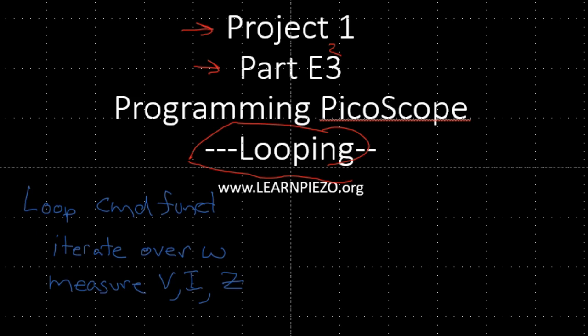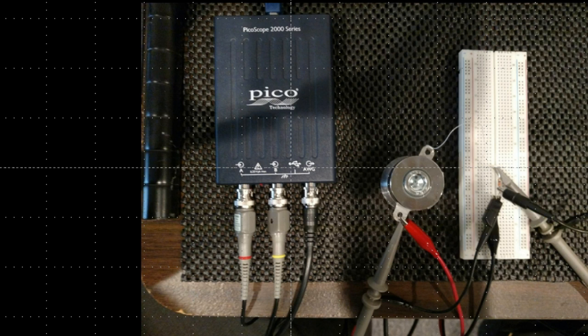So let's first go into the experimental setup as you see here. We have our Picoscope. We have channel A, or channel 1. We have channel B here, and we have the arbitrary wave generator, which is our function generator, which is going to be supplying the signal that we're going to use to exercise this piezoelectric transducer here. Let me draw a schematic diagram of how this voltage probe and this BNC to alligator clip are all going to connect together.